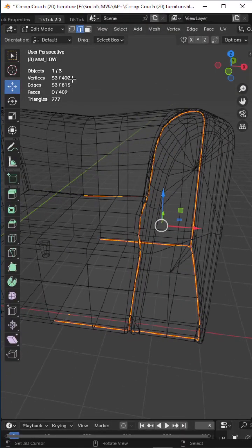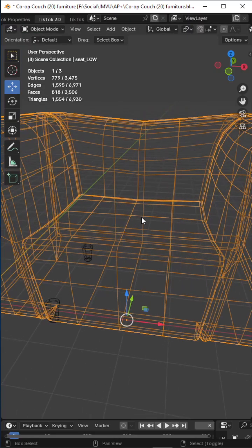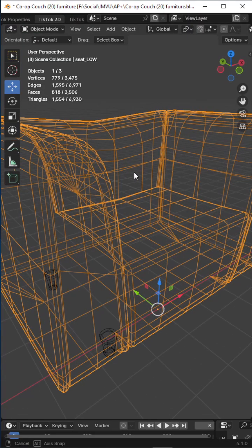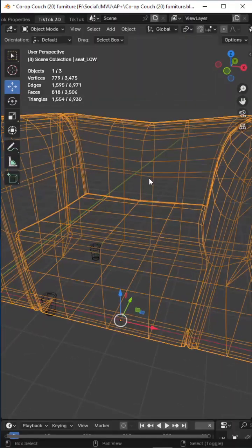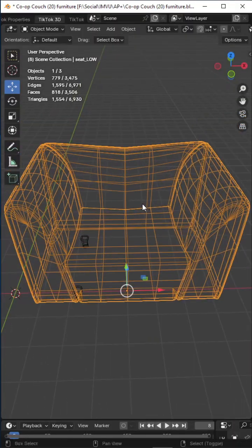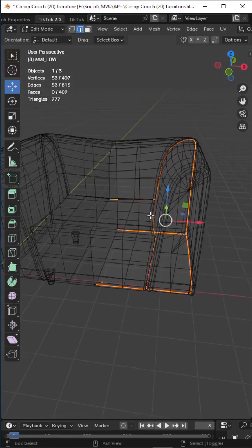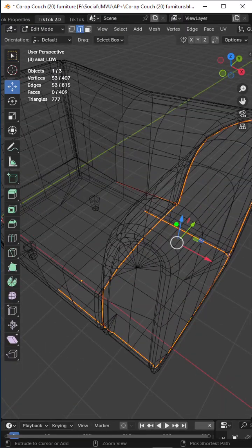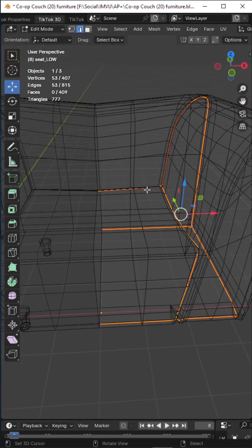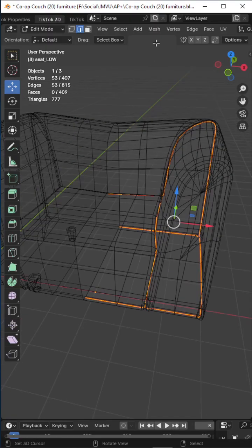If we just check something, toggle out of object mode. We want to be aware in this particular instance that we are mirroring this mesh. So this is the original half, and it is being procedurally mirrored, which means any editing that we do to this side of the mesh is being automatically done to the other side. So there's a point here about mirrored meshes.